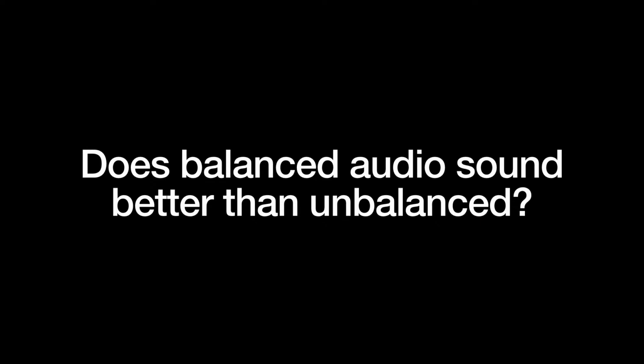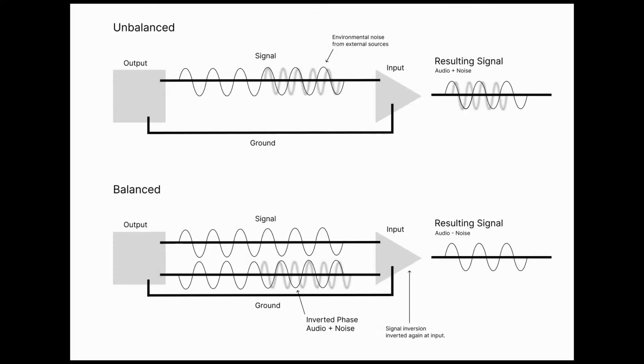So that's where this is a little bit of a trick question. So thanks everyone for taking the poll, and everyone that took it is basically right, because you can argue it both ways. So it isn't really necessarily balanced sounds better than unbalanced. It is that balanced is more immune to RF and electromagnetic interference than unbalanced cables are. Let's talk about what that means in practical terms. We actually already answered that question, so we're going to jump right ahead here.